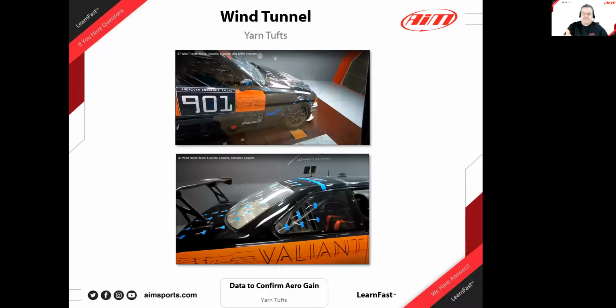Very cool. Does taping up seams between the hood and the fenders make any real significant difference in aero? Yeah, like I mentioned earlier, the first run we did where the hood popped up and the car ended up making lift, the front made 45 pounds of lift, and then it went down to about 20 when we made sure the hood was closed. So that just kind of goes to show that even if you tape the gap between like the headlights and the grille and the hood, yes, you should see a little bit of a gain from doing something like that.